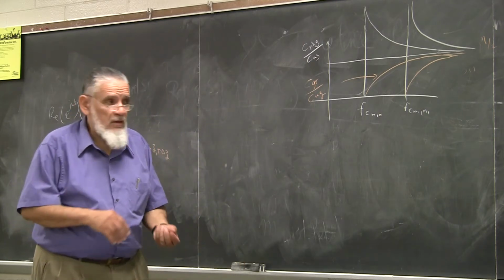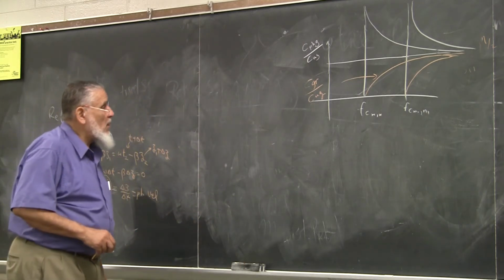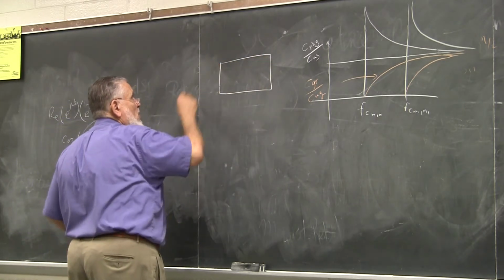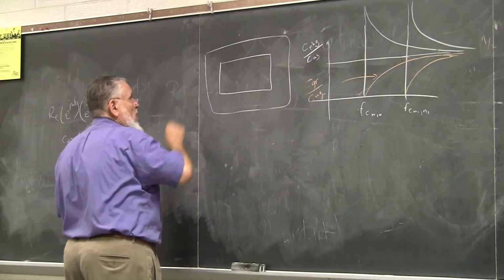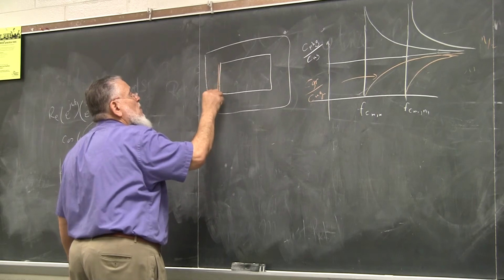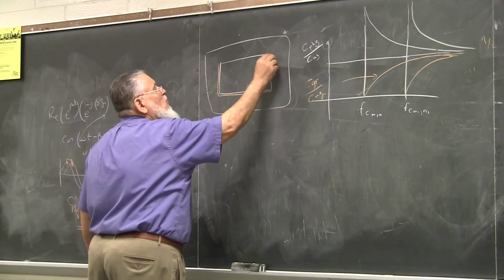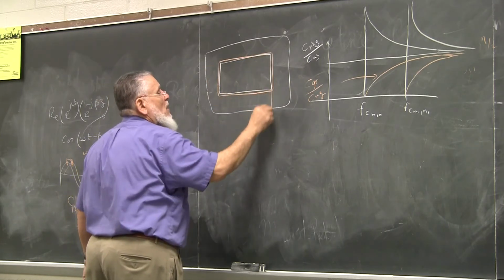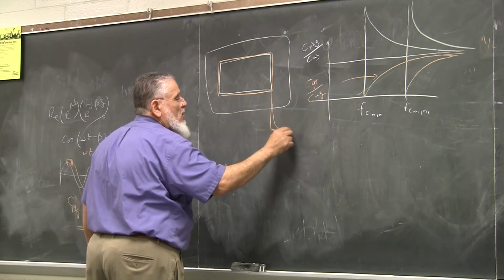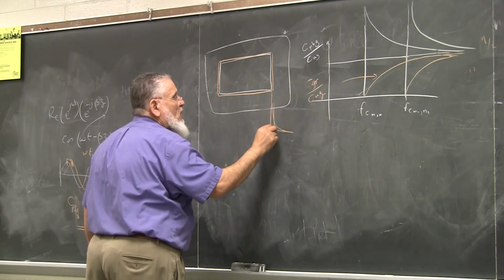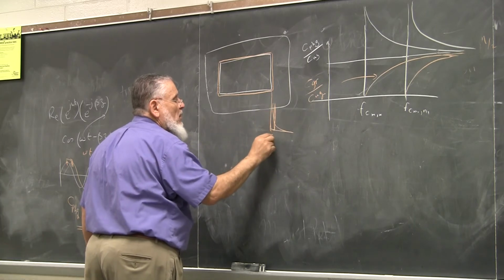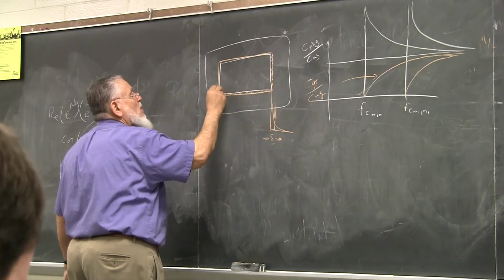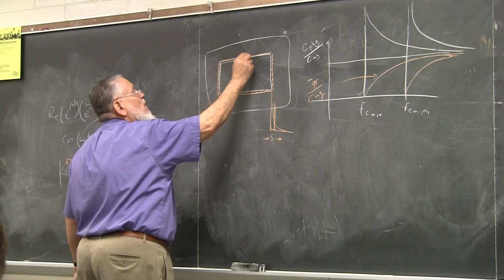Actually, silver conductivity is better than gold, right? So there is some losses in the guide, and that's because of the skin effect that you have in there. So if you go in the guide body here, right, your signal is going to penetrate, and we approximate the penetration by the skin depth. You know very well that the signal actually attenuates exponentially down, and we average things to what we call delta. Delta is the skin depth. So the resistivity of the skin here has to be entered in the equations,